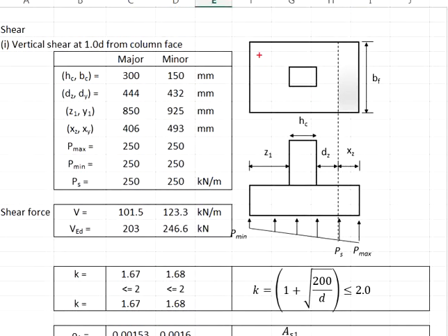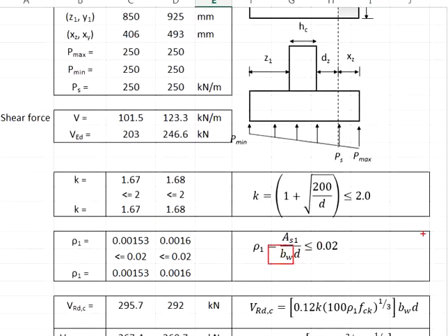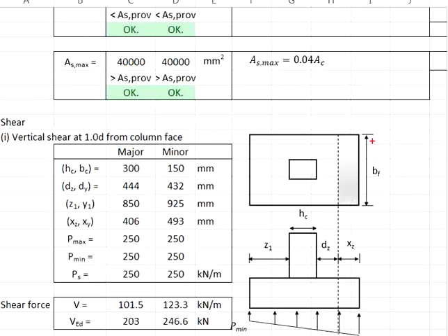Let's say we are talking about this pad footing. The reinforcement bar in the major axis will be arranged in these orientations. The reinforcement bar shall pass through the shear plane here, and this reinforcement bar will act as resistance together with the concrete at this plane. Because of that, the b here shall refer to this width instead of this.